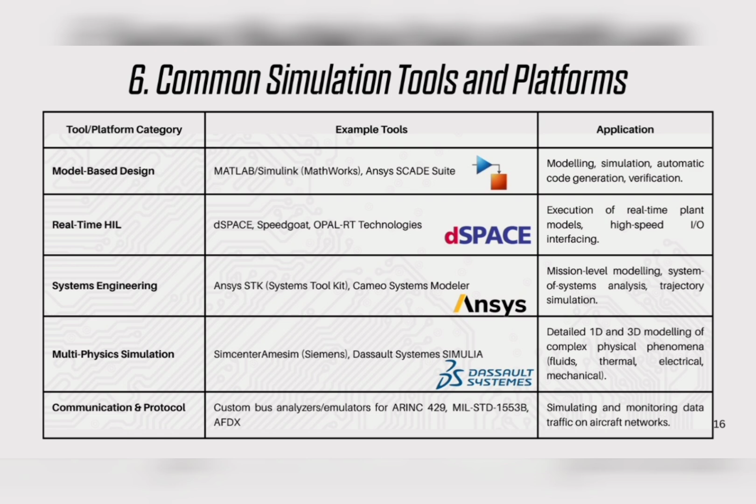For multi-physics simulation, thermal, aerostructural, electrical, Simcenter, and Dassault SIMULIA are used where fluid, thermal, or mechanical coupling matters. For communication and protocol testing, specialized bus analyzers and emulators for ARINC 429, MIL-STD-1553B, and AFDX validate message timing, latency, fault tolerance, and arbitration.